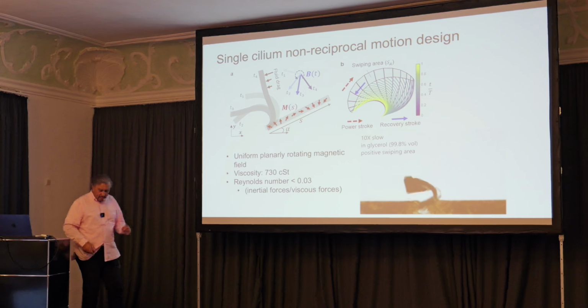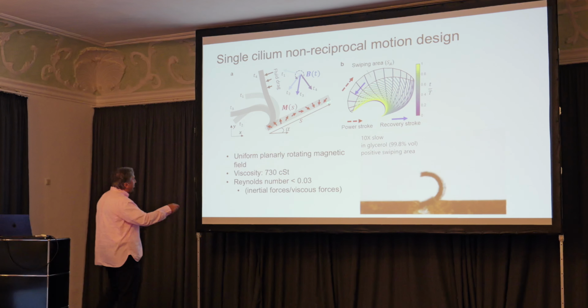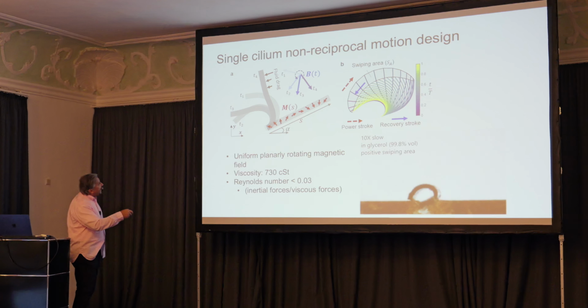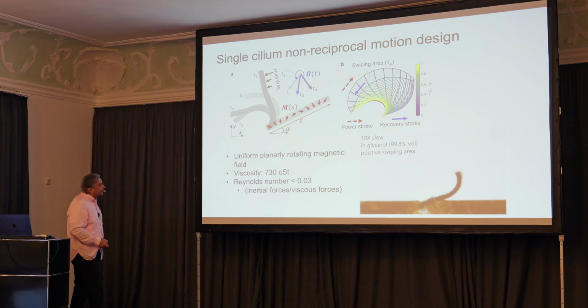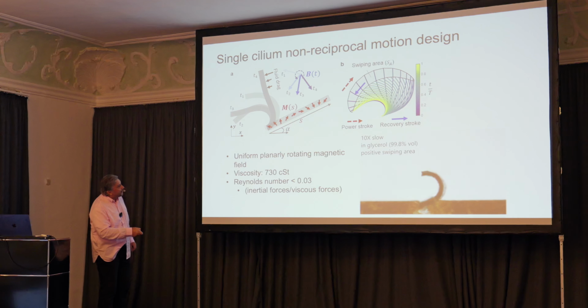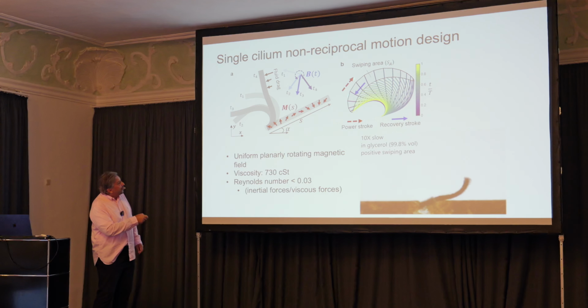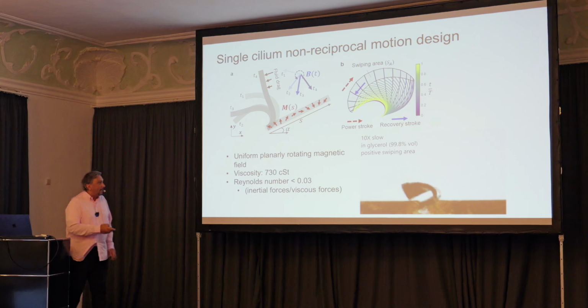It's very simple. As I mentioned, the phase difference trick. At the beginning, when we fabricate this waveform, you can change the phase difference by wrapping it differently. And now, for one beam, for example, if you apply a field left and right, you see the deformation. This is very low Reynolds number now, because cilia work at very low Reynolds number. Left and right sweeping is not symmetric, so we need to be non-reciprocal, as you know. And the larger the sweeping area difference, the more fluidic pumping happens.